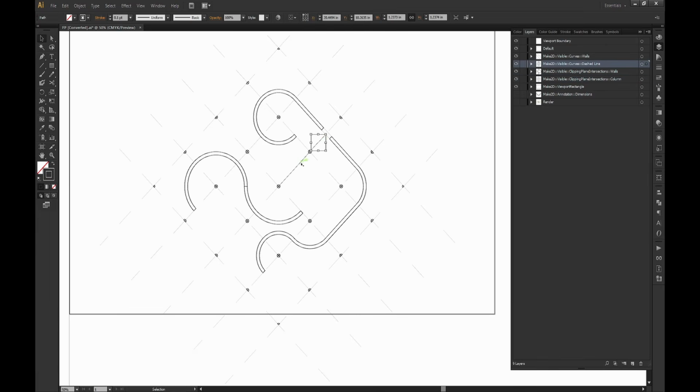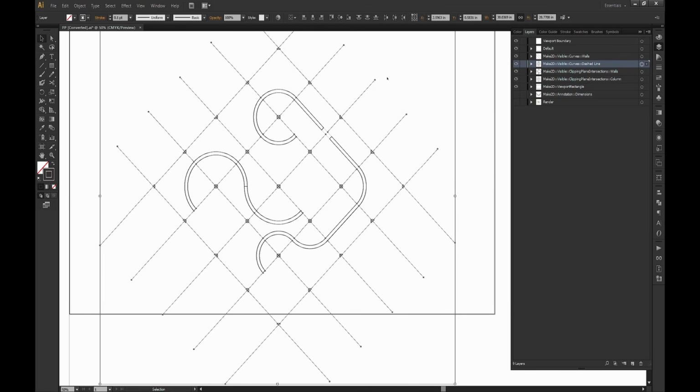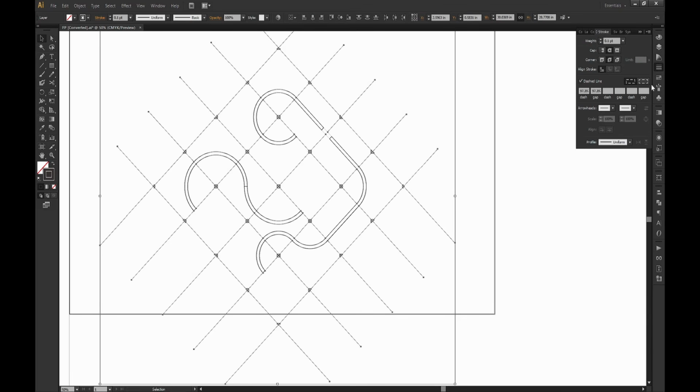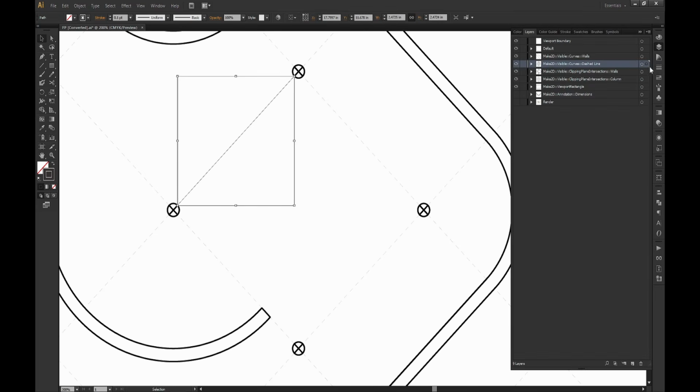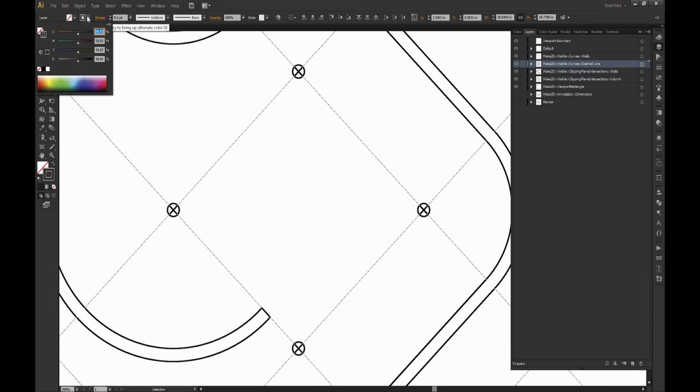And these are my dash lines right here. You see these guys right here. If I click on dash line, I'm going to select them all. And I'm going to go to my line type here, and we'll make this nothing. And then maybe make this like 6 to see how it looks. Let me zoom in on here. That looks nice, but it's just very light. So I'm going to go back to here and just change the color of this. Let me just make it 0.25. I would make it maybe like 80%.